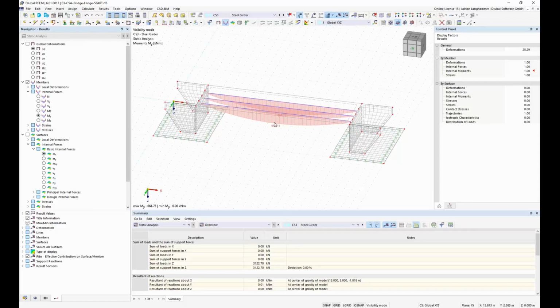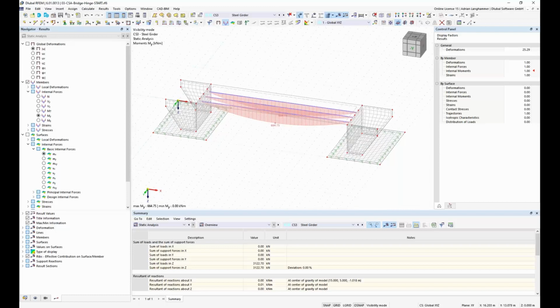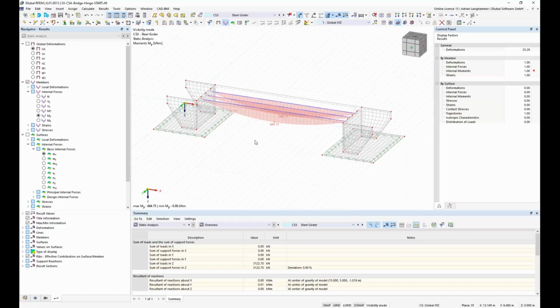It is also now possible to reactivate elements. This could be useful, for example, if you want to simulate renewal of a structure where you remove old parts and add new parts at the same place. This was also not possible in RFEM 5. As we saw in the main example, it is possible to use the automatic combinatorics or combinations of RFEM in combination with the construction stages.